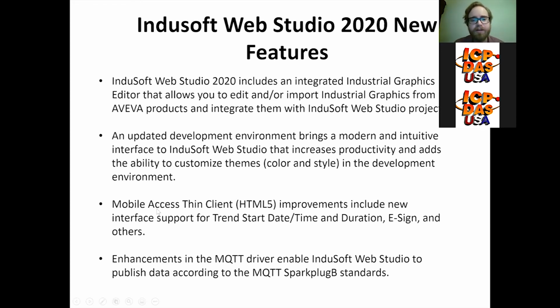Like I talked about with the thin clients before, mobile access thin client improvements include new interface support for trend, start, date and time and duration, eSign, and others, and enhancements in the MQTT driver enable Indusoft Web Studio to publish data according to the MQTT Sparkplug B standard. So a couple quality of life improvements there, in addition to the fact that all the thin clients are now HTML5 based.